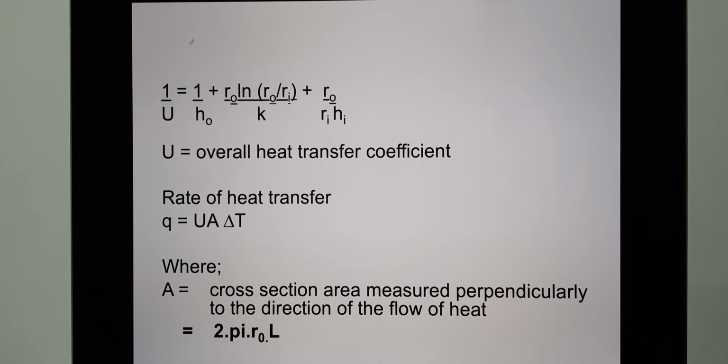When you have calculated 1/U, that's not the end of your answer. For example, if the value of 1/U is 10, you need to calculate for U. How do you calculate U? U is 1/10, so it becomes 0.1. What is the unit? You need to ensure the unit is correct as well. U is what we are interested in.